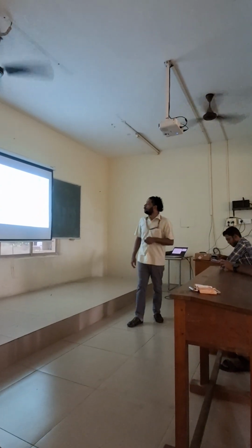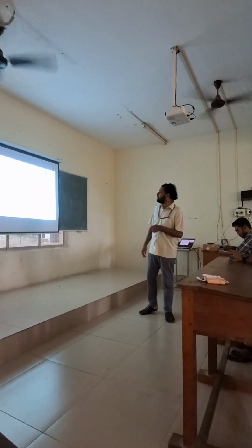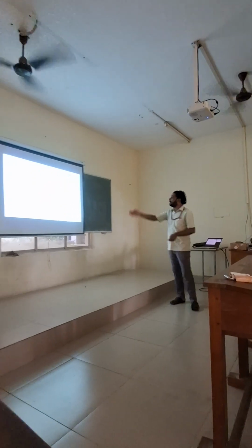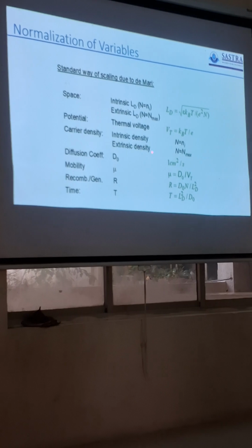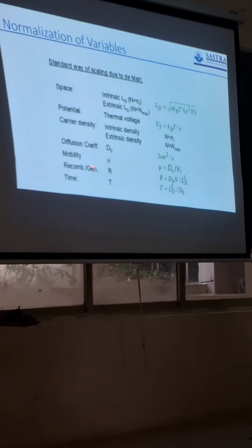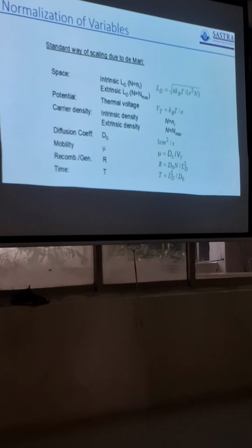Therefore, at the quasi-Fermi level, we use these kind of numbers. N is the electron concentration, P is the hole concentration. And these are basically the Debye length, that's the expression for it. The thermal voltage. This is the free flight time that we can maximum simulate.